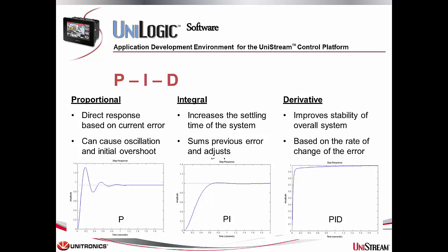However, too small of a proportional band will create an overshoot and oscillations around the set point, and too large of a proportional band will not allow an efficient response to the system, or riding right below the set point.